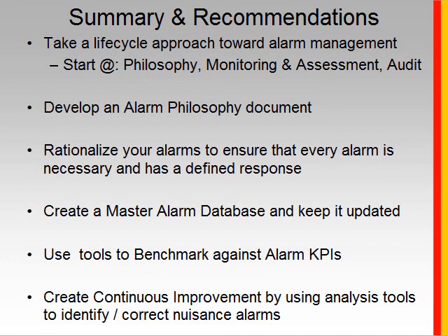Philosophy is best to start with if you're a new plant or a new system. If it's an existing system, then probably monitoring and assessment is the best place to start, or audit. Monitoring and assessment will help you figure out how your alarm system is performing, compare it against the benchmarks of the standard, identify nuisance alarms, and determine what you need to do to get back to the performance level.